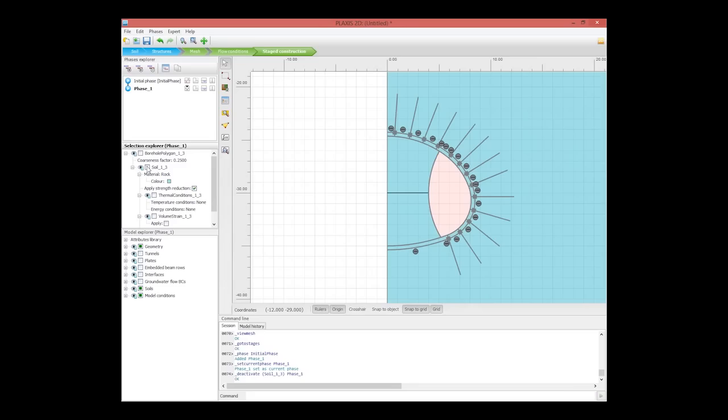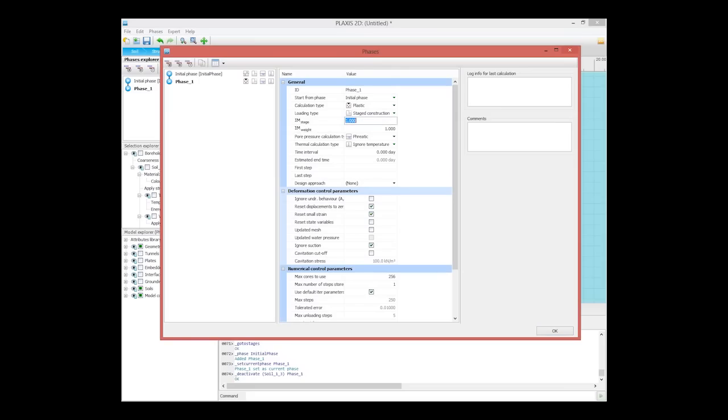So this is usually addressed in a 2D application by considering a sum M stage which is not equal to 1 but equal to some lower value, such that at the end of the phase there is still some soil pressure remaining onto the side of the excavation. This can be done in PLAXIS by changing the sum M stage factor to 0.5, meaning that at the end of this phase there will still be 50% left of the initial soil pressure.